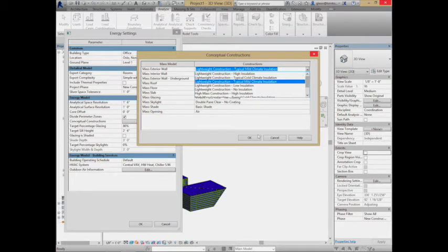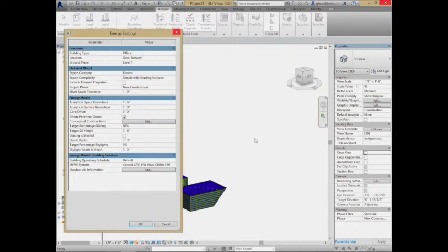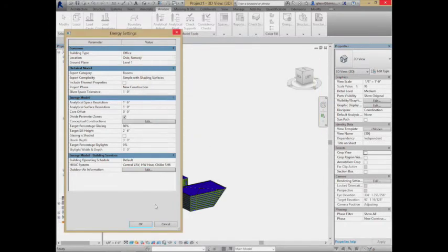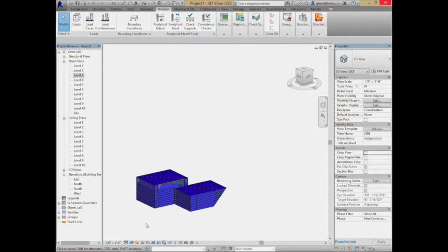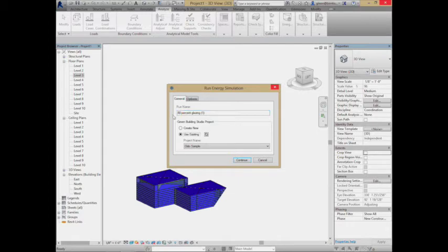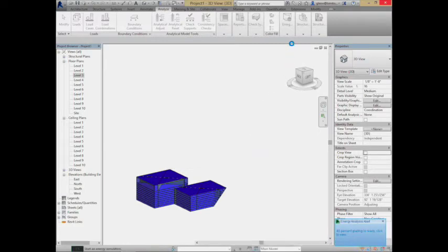We'll do the, let me do the 80. Let me run that one, and then I'll go back to 40 and put in the high insulation and see what the effect of that is. Okay, so I'm going to run this 80% glazing building. And then finally, I'm going to switch back to 40% and see what the effect of, 40% is already ready. Let's send that one off.